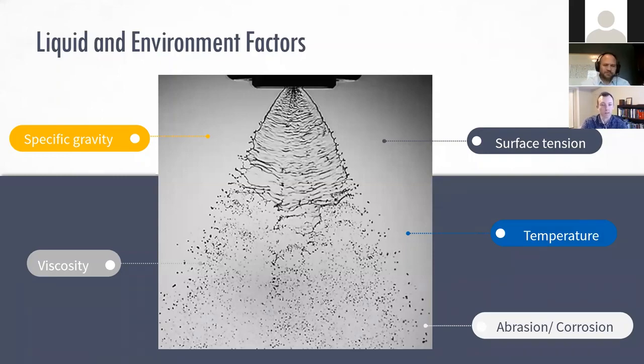Yeah, and one of the things we can do, Justin, just to touch on that, is not only measure or look at how a material might spray with a nozzle, but we can also generate, say, a temperature viscosity curve for a material, right? So you might hit some critical point where if we could just have 5 to 10 more degrees temperature increase, like you say, something's going to spray a lot easier because the viscosity curve is really falling across that temperature range. Yeah, there's a critical point.